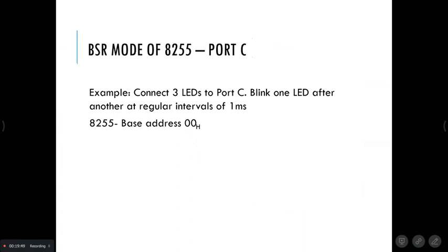Three LEDs are connected to port C, so you have to now use bit set reset mode. You set those 3 LEDs one by one. What is the question given to you? Blink one LED after another at a regular interval.